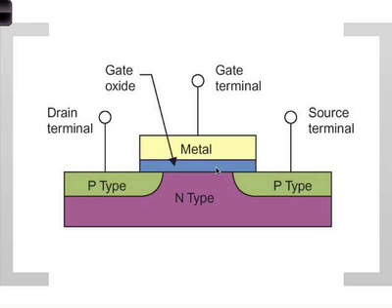Yes? There's no physical difference between drain and source, right? That's correct. It's symmetric. It's purely symmetric. In fact, we will look at how they are fabricated. No physical difference. So even if you messed up and did source to drain, you really wouldn't be messing up. You'd be doing drain to source, right? That's correct. Except that when you start connecting them in circuits, you cannot mess that up. Well, yeah. Because you have to have a common ground voltage. Right. But otherwise, you're right.